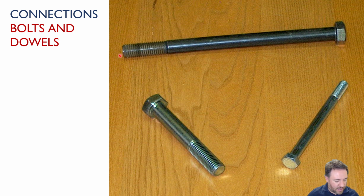You might see them in diameters, for wood applications, usually on the order of 1/2 inch or 3/4 inch. You could potentially see up to 1 inch for really big members. That would be a pretty large bolt to use, though it's kind of the larger bolt that you use for steel design, a 1 inch diameter bolt. It could be up to 1.5 inches, but that would not be very common. For smaller timber connections, a 1/2 inch bolt that looks something like this is probably a common type of bolt that you would see.